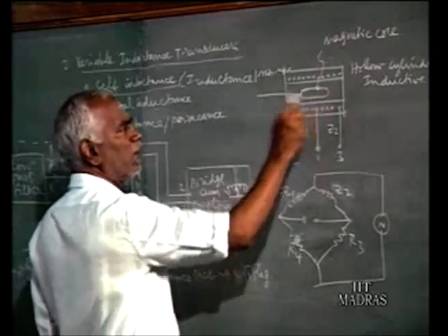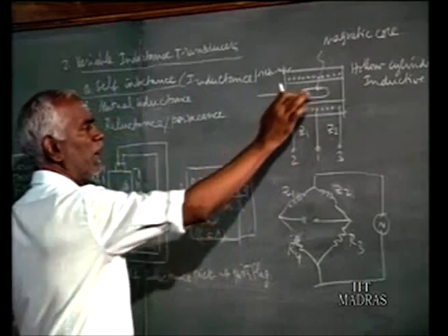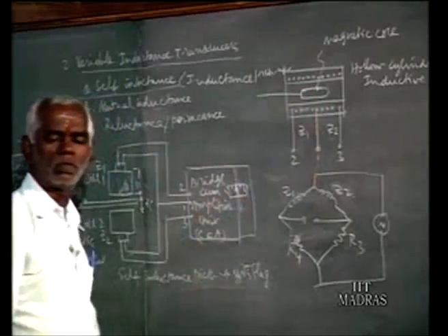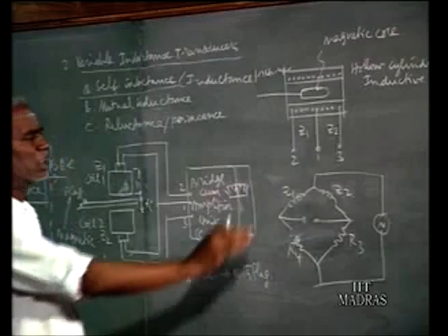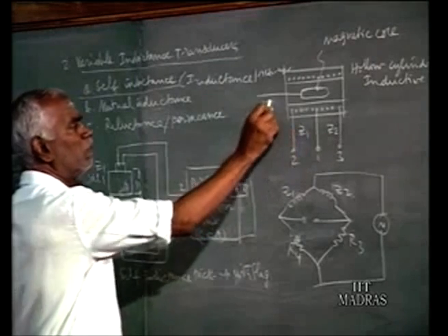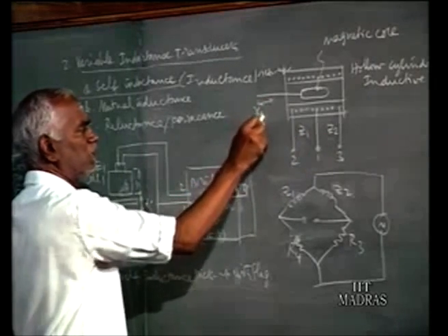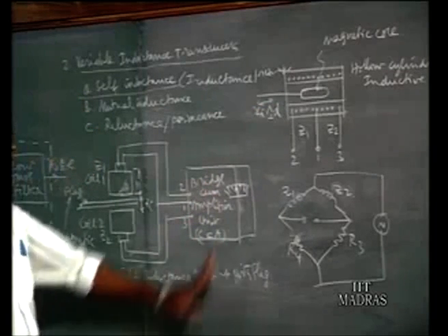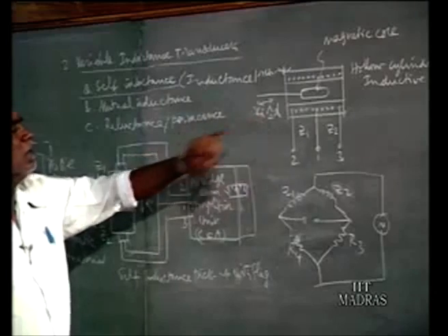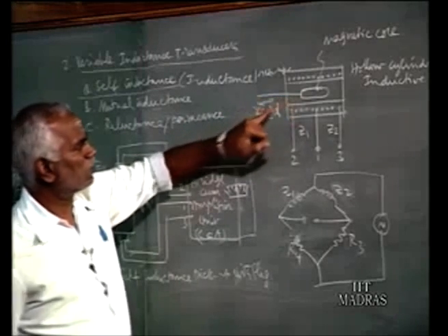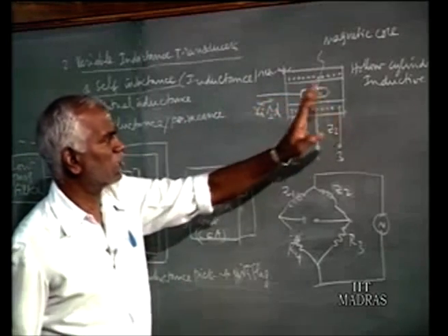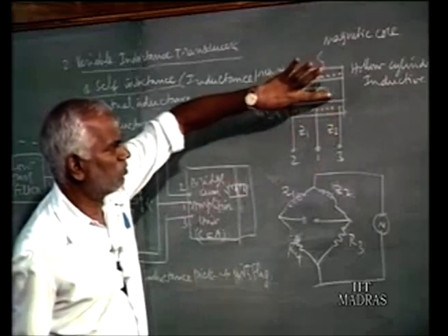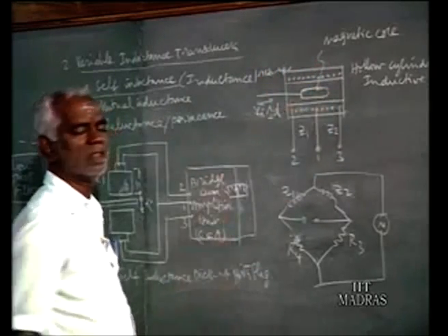Now when the magnetic core is at the middle, we find magnetic material distributed equally to both the coils. So impedance Z1 and Z2 will be the same, and if we move the core by giving Xi displacement, Xi is the input signal, the same as displacement, because it's a transducer for measuring displacement. When you give the displacement here, suppose we move from left to right by some small x, of course the displacement is limited within the length of the total coil.